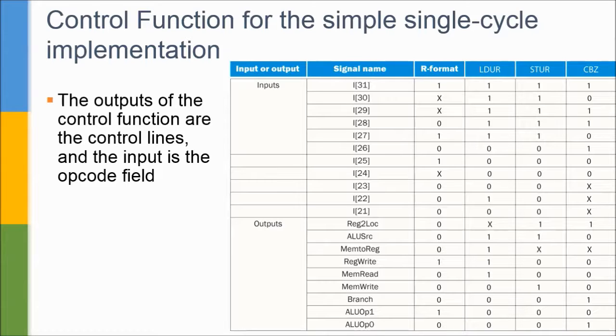So we see that when we convert an R format instruction into its binary form, then bits 21 to 31 show the opcode field. So we have 1XX0101XX00 bits common for all the four operations that are add, subtract, AND, and OR. The X's indicate the bits 30, 29, and bit number 24 are different in these four instructions.